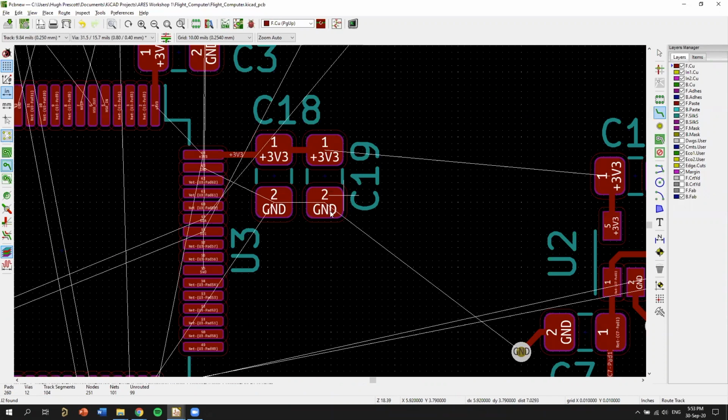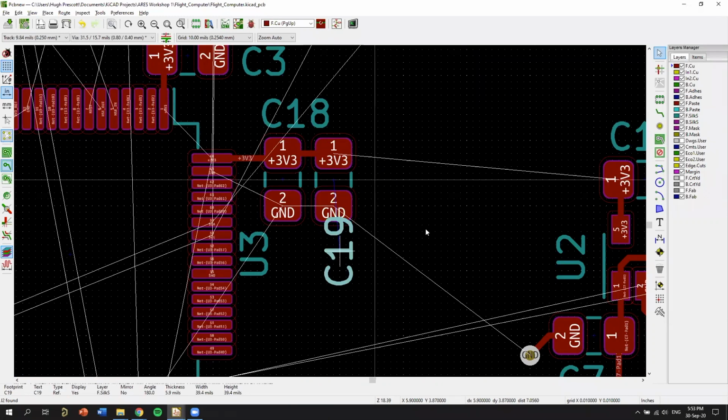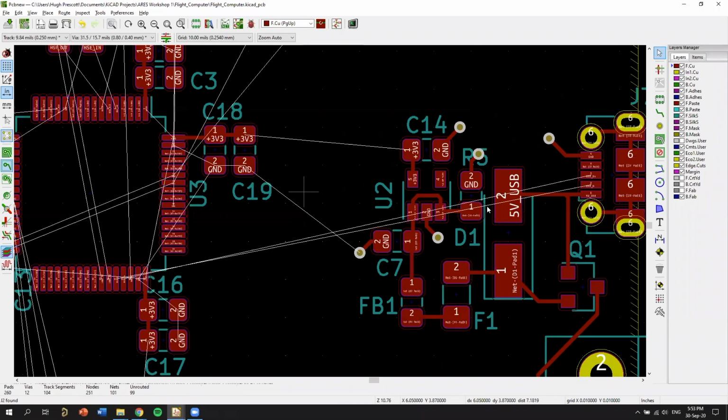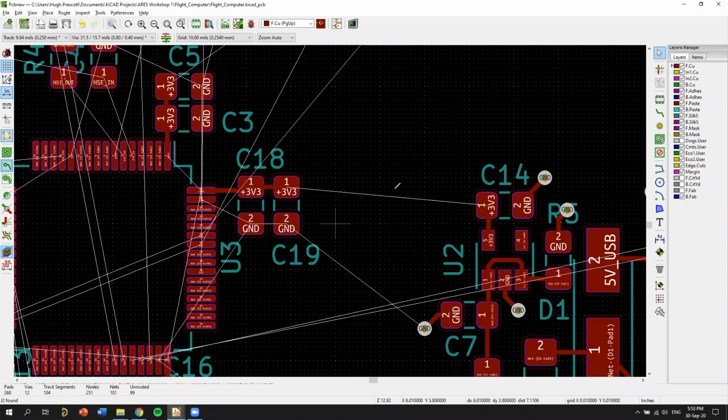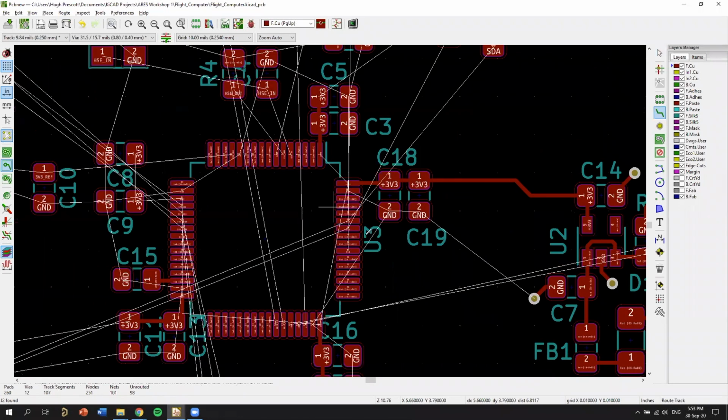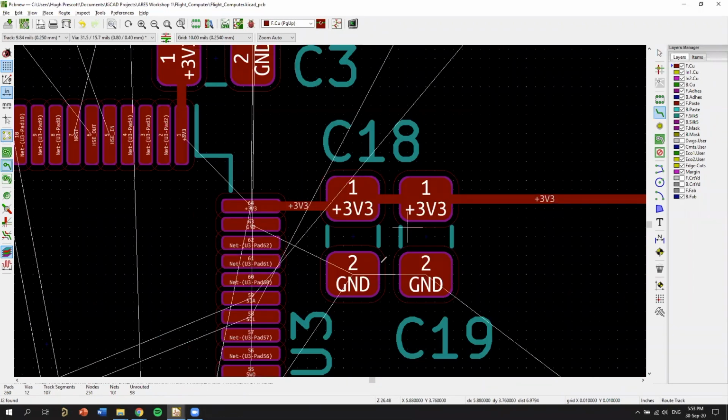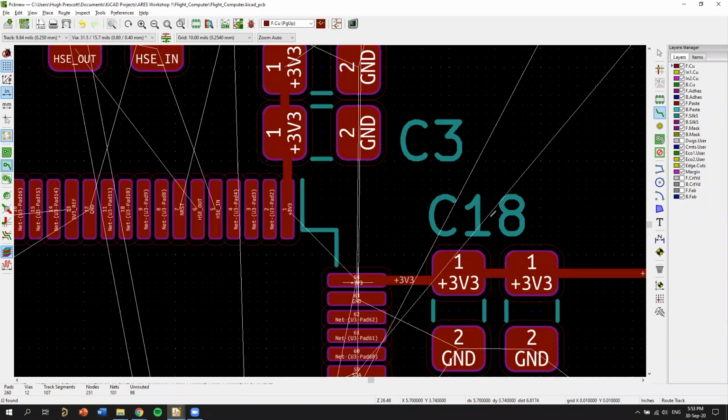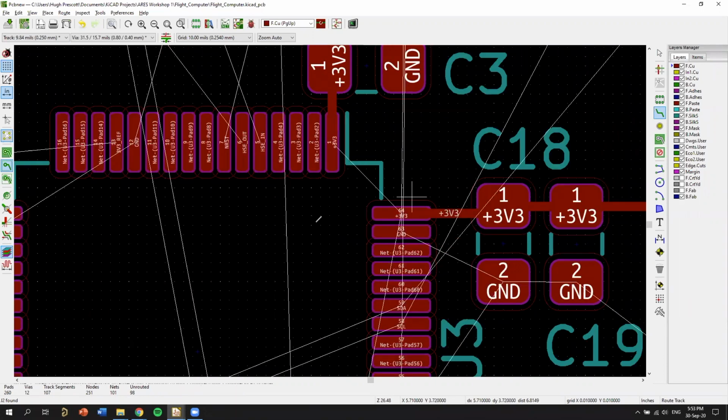All right. And then for the sake of connecting things, we have our output of the 3.3 volt regulator, and it's going to go into here. And so now we finally routed our power into our microcontroller, at least at one corner. But think about how best to provide power to each corner.